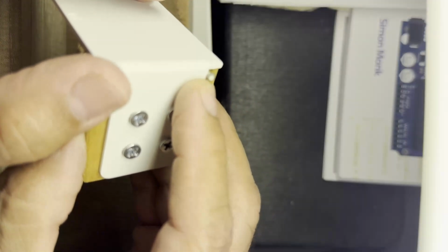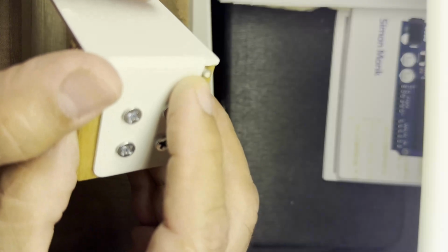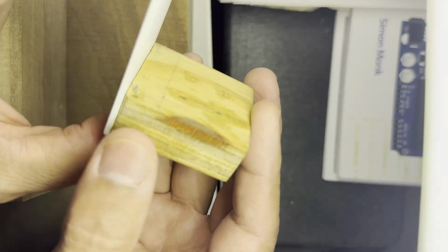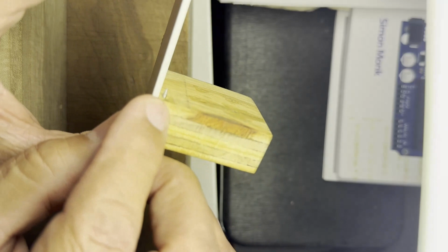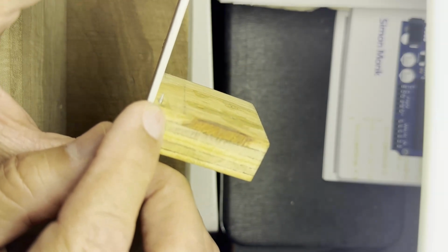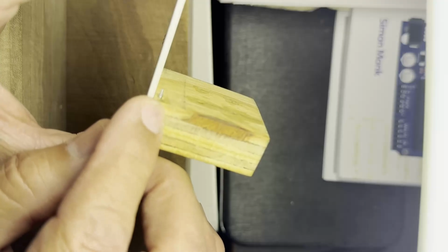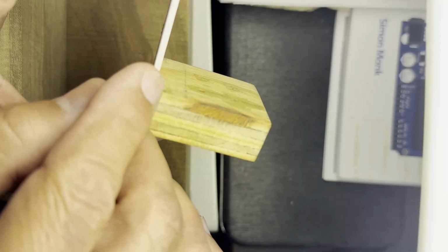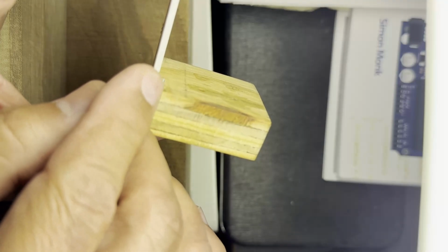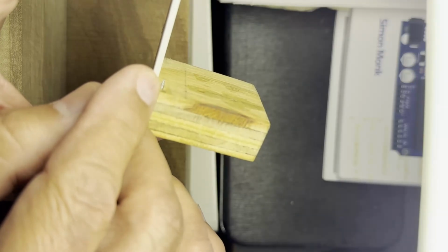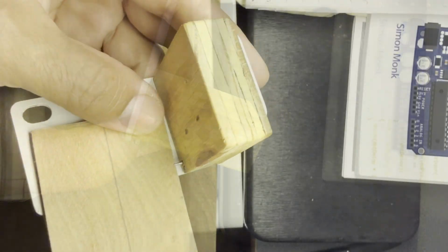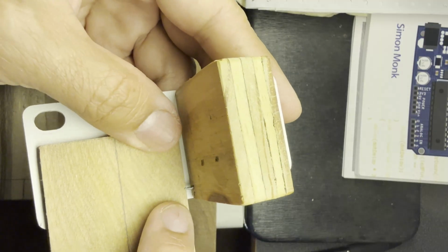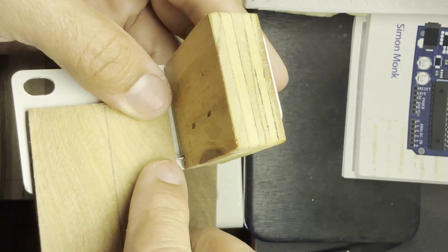For the scribe, all I'm using is a piece of nail. That is it, just a piece of nail. And to give this exact 2.5 millimeter distance, what helps is a 2.5 millimeter plywood piece, which I kept between the tip of the scribe and the surface, so that gave me an exact 2.5 millimeter gap. So here's a 2.5 millimeter piece of plywood. You just knock it in right on that tip.